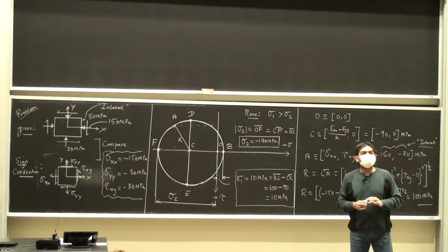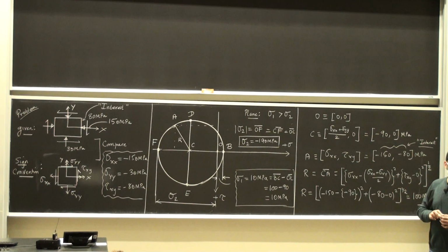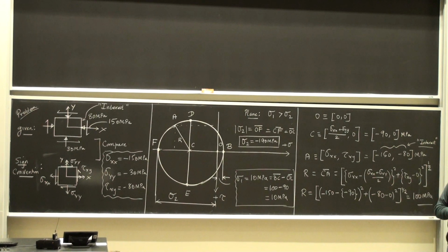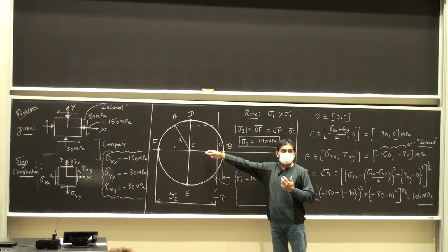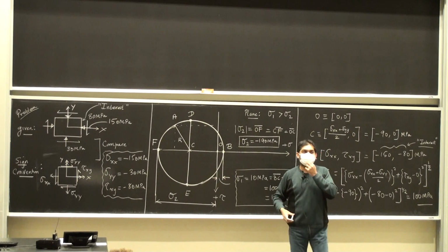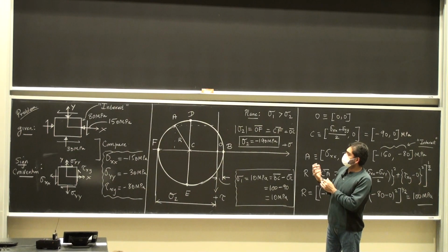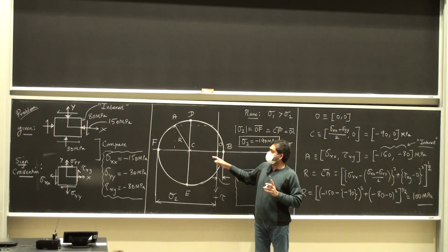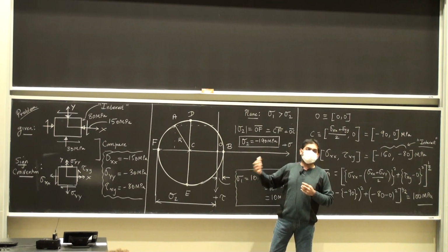And if we're on the exam drawing the Mohr circle, let's say it doesn't cross the y-axis, so it doesn't reach the origin. Like, for example, I didn't draw according to scale. Would we lose points for that, or would that be sufficient? So, for example, you're saying that this is the problem you're solving in the exam, but then this point is sitting there. Yeah, that will be wrong. Absolutely. Because you can visualize that the distance from O to C is lesser than the radius, isn't it? Which means that there has to be a part of the circle that's going to extend onto the positive side. So that's one way of thinking about it.